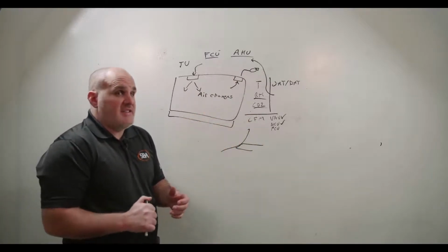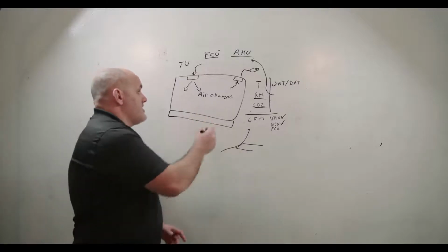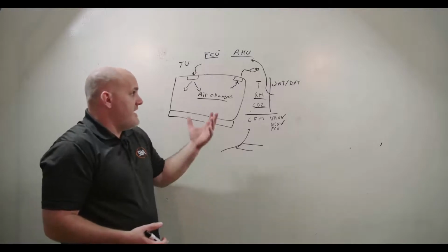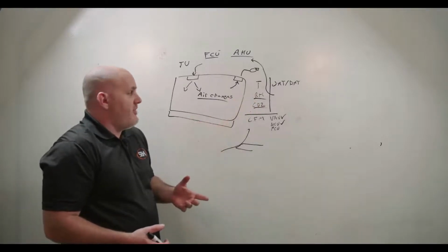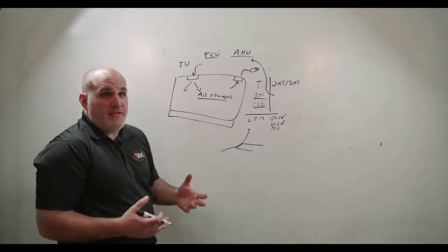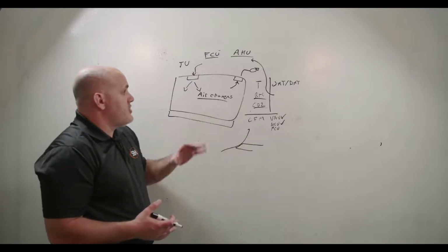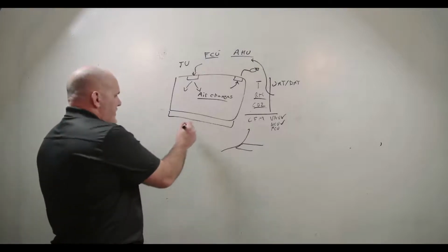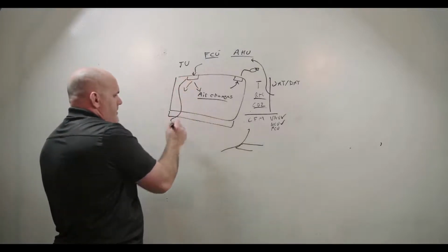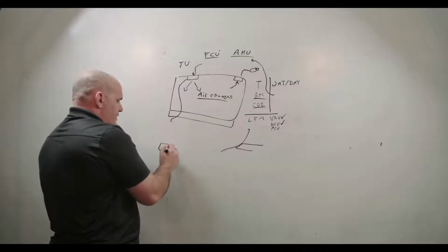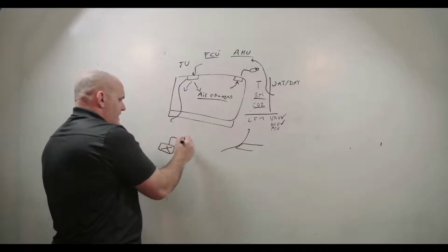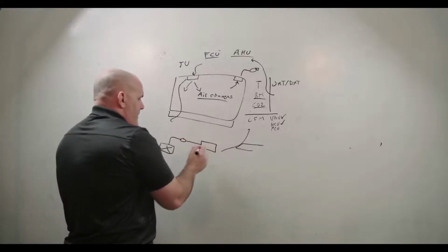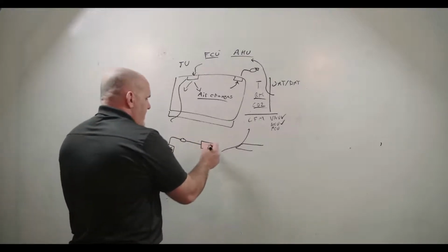And in that case, we want to understand first that our air changes and our air volume are what are going to cool the space, heat the space, impact the relative humidity of the space, impact the CO2 levels of the space. So we want to make sure that we have air volume properly controlled. How do we do that? If we kind of blow this up right here, what we would see is we would see a diffuser, right? We would see that going into a balancing damper, going into a VAV box.